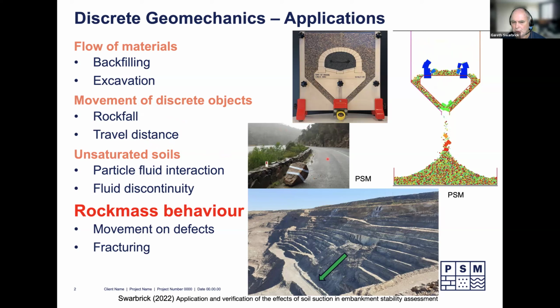So we often build sometimes very high slopes, up to hundreds of meters high, and we're concerned about blocks that may become dislodged from those slopes. And what's the travel distance of those blocks? Understanding the size and the travel distance allows us to design fences and other types of systems that can retain those blocks and prevent, or certainly limit, the size and the impacts that they might cause should they become dislodged. So by using approaches and modeling, we can look at different types of retaining systems and decide which ones might be the most effective and most appropriate for that particular geological environment.